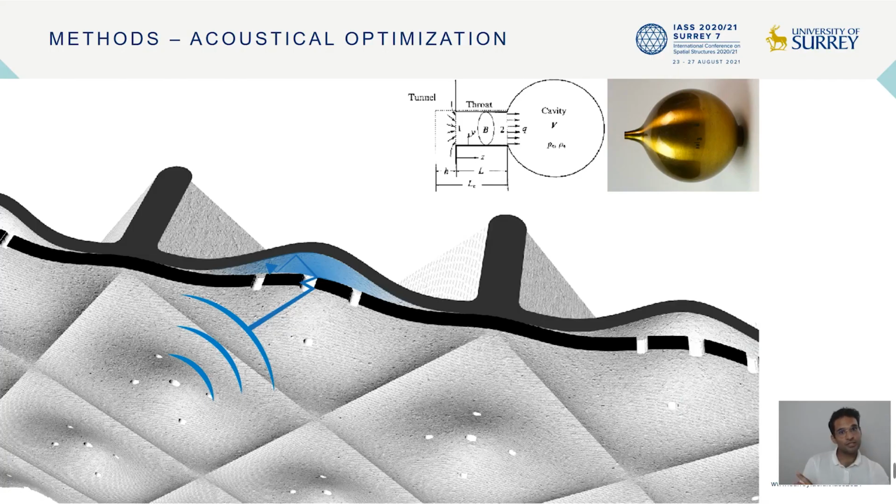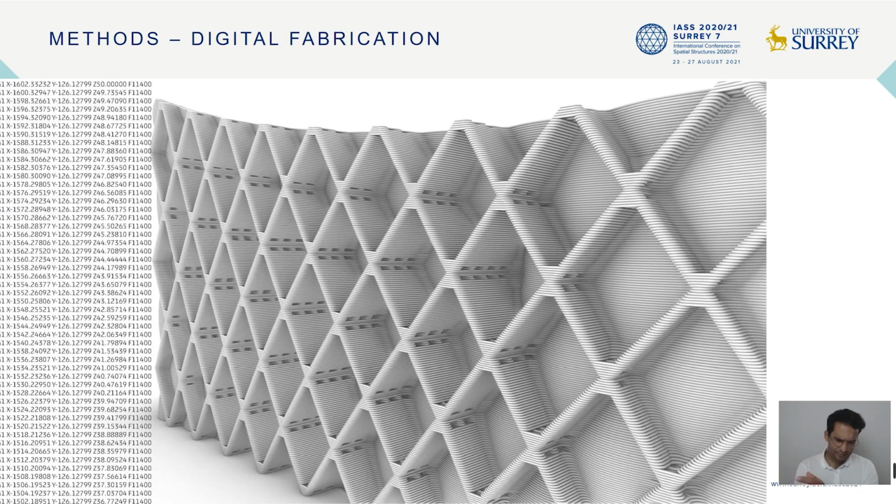Another innovation alongside the structural optimization was the acoustical optimization. We implemented small voids that are actually adopting the Helmholtz resonator functionality, where you have a difference in air volume, and then hereby you can absorb frequencies ranging from 100 to 2000 Hz, depending on the usage that you want to have, which we can then actually fine-tune as we go along. This is how it looks.